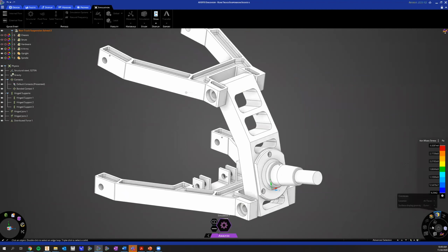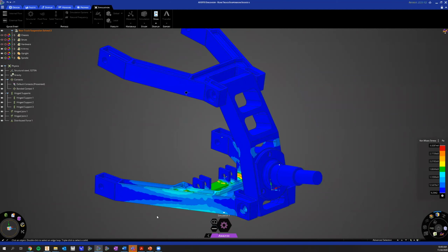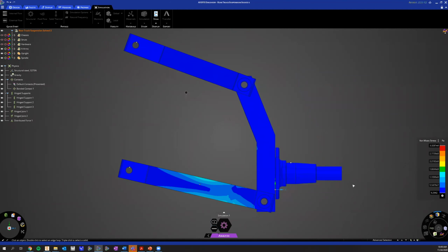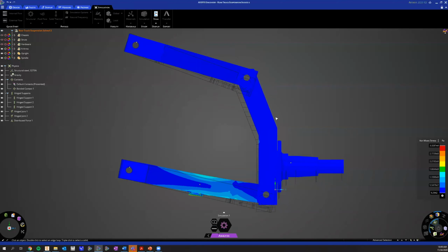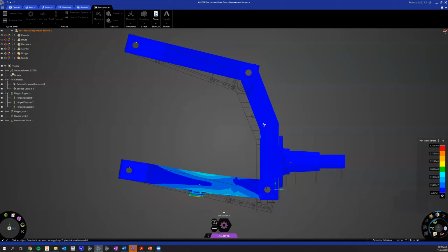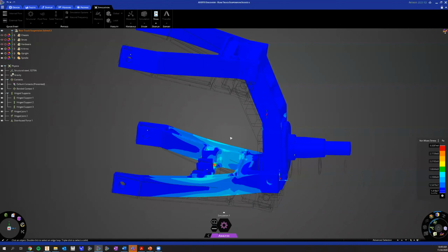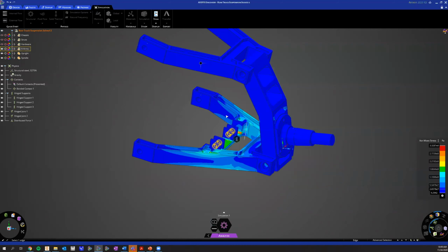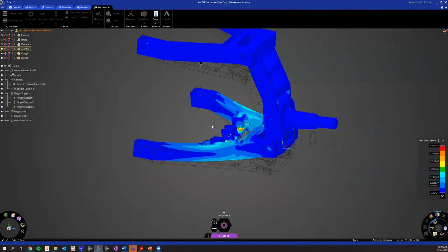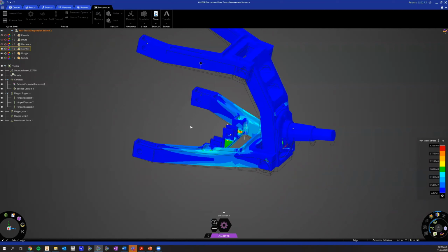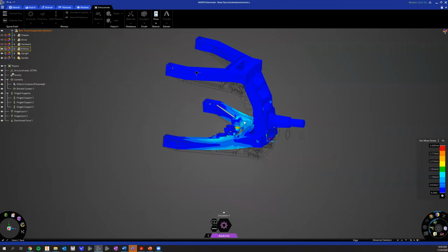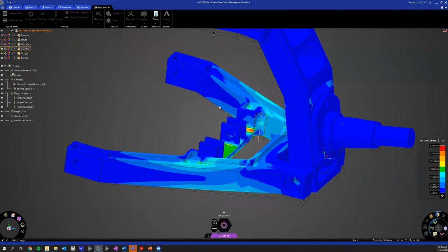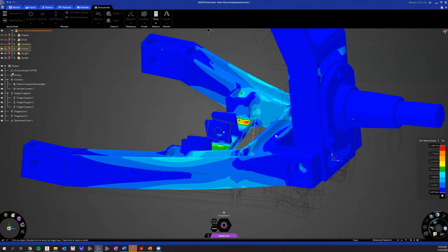What you see here are simulation results for this, but instead of everything being bonded together, there's now a hinge relationship, so we can exaggerate that deformation and take a look at this. And this is a case where the strut and the suspension has been bottomed out, and assuming that maybe we needed to do a design change to our suspension itself, also optimize these areas, because if the strut and the spring bottoms out, then we're going to get really high stresses in this area.